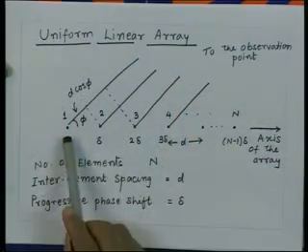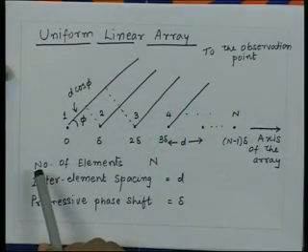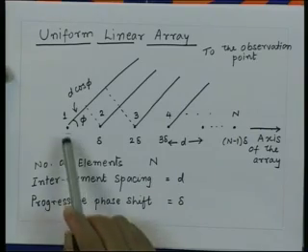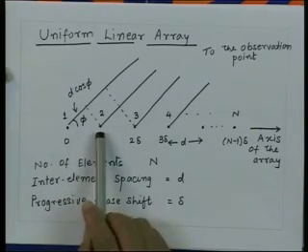We are discussing a very important topic in antennas, what is called antenna arrays. First we saw some broad characteristics of a 2-element array, and later we started investigating what is called a uniform linear array. So, we saw in the last lecture that we have a uniform array which is excited with equal amplitudes. The spacing between adjacent elements is also the same,